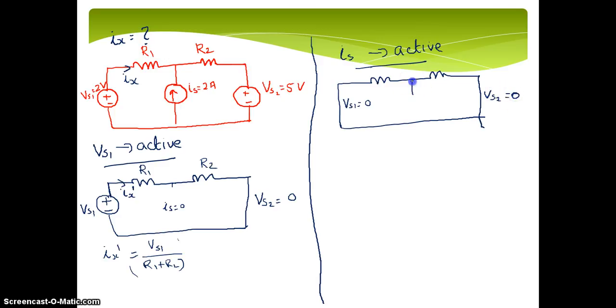And you have the current source. This is the only one active now. So it is a 2 ampere current source. It is there. And you are interested in calculating the current thus. Now this is due to only the second source, so I will represent it as Ix double dash. This current is dividing into 2 branches. By using current division you will get Ix double dash.